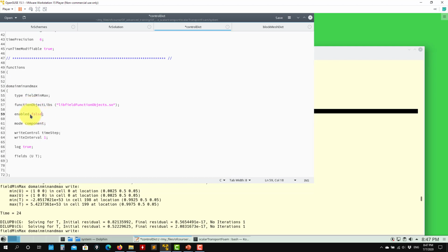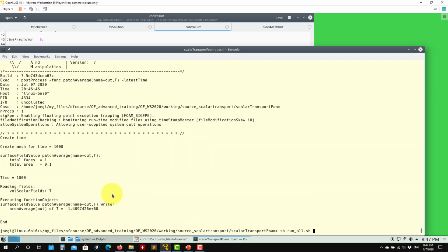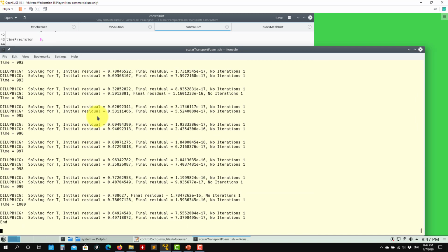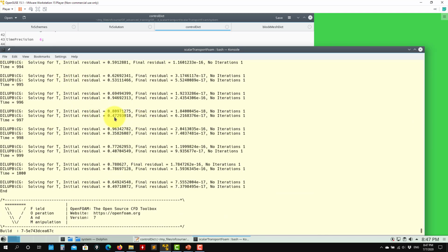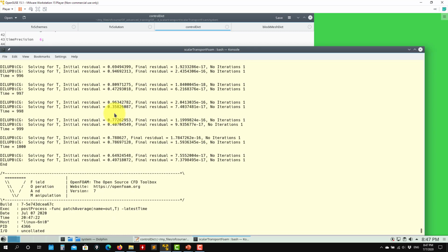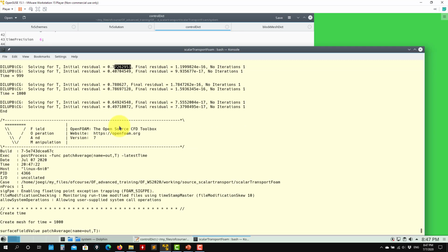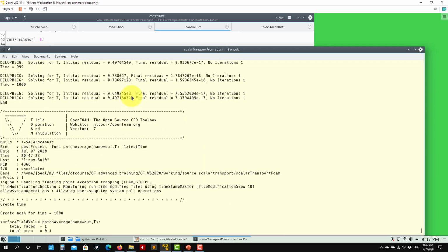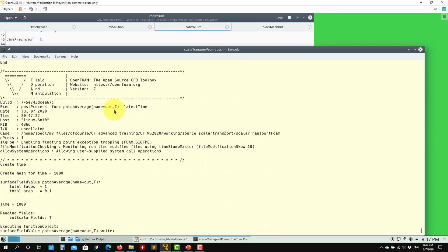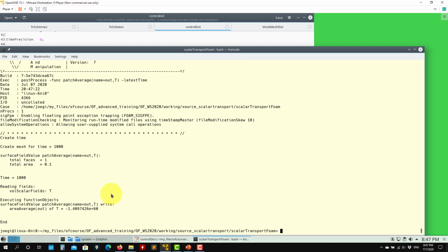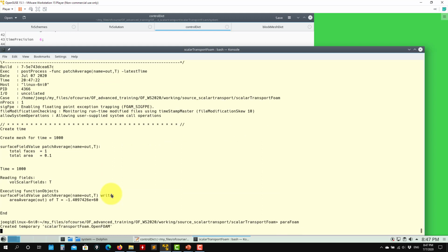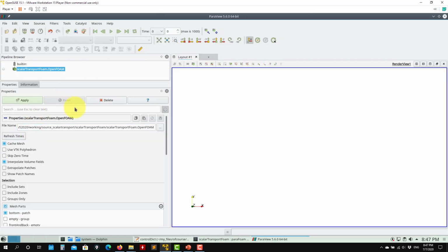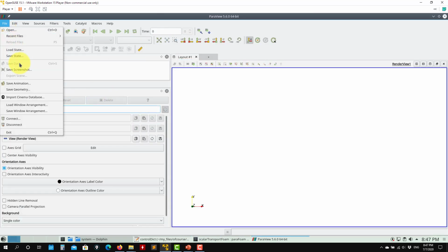If you are running without this one, you will go like this. See that you don't have any information on what is going on. For you, it will be, okay, it's converging. Maybe you will look at the initial residuals and realize that they're a little bit high. But sometimes even these residuals can be low, and you just realize at the end that your solution is completely wrong. So my advice, again, is to always monitor those minimum and maximum values.